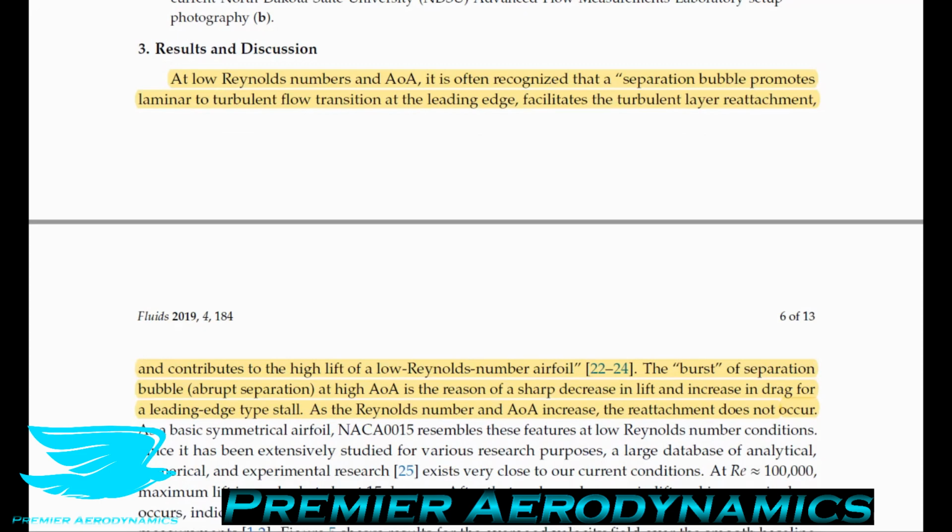I've talked about laminar separation bubbles quite a lot in podcast number 11. So if you want, go check out that. It's called NACA 4412 laminar separation bubble. But let's talk a little bit here about what a laminar separation bubble is, or a separation bubble in general. So what this is, you have the flow going over a leading edge, and it's laminar. Then it detaches, and then in that detachment region, when it's flowing over still, it will transition to turbulence and then reattach. And in that detachment region, you get this recirculation bubble.